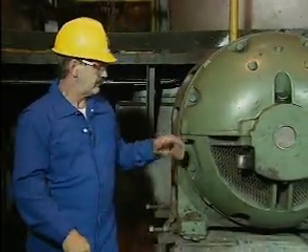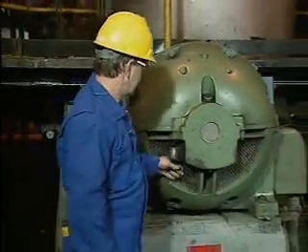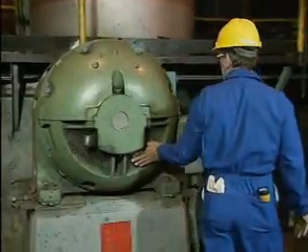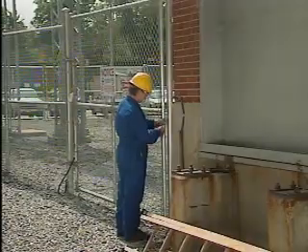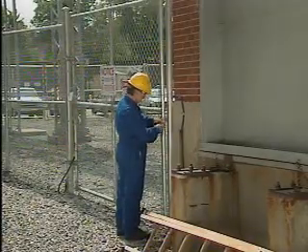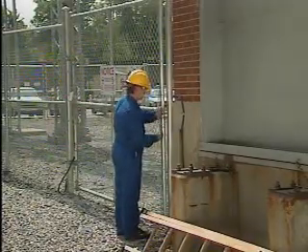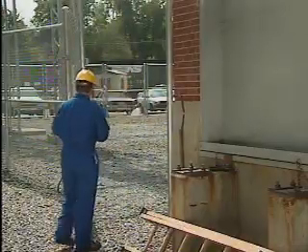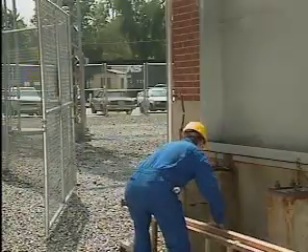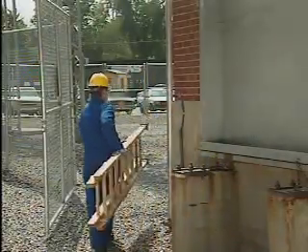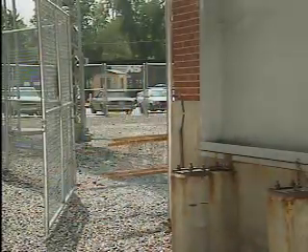Whenever you work around any equipment that is or may be energized, you need to be on the lookout for electrical hazards. For example, moving or working on ladders near energized components can be hazardous. If you're not careful when you're moving a ladder, it's easy to hit electrical equipment. In addition, just being on a ladder means that you're closer to circuits than you normally would be.